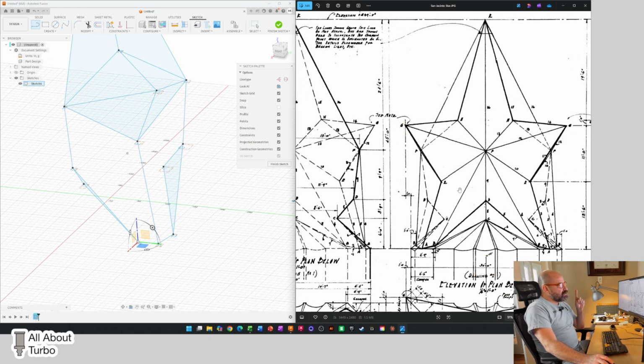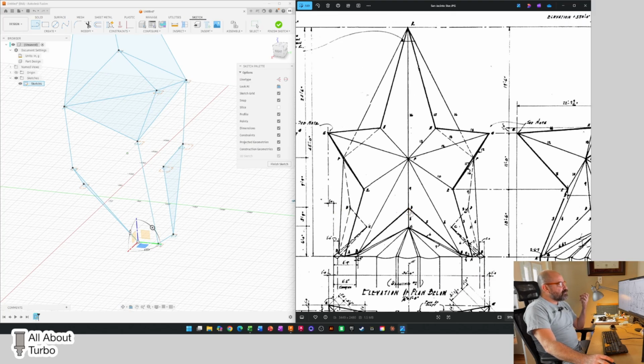And this is the only thing I would think, I don't want to call it a flaw, but when you look at this leg, the points A, B, F, E, there are 4 points. It's a trapezoid, not a triangle. It's the only feature in this drawing that is showing up with 4 points. Now, based on fundamental geometry principles, you need 3 points to define a plane. And if you add a fourth point, you start getting in trouble because that fourth point, unless it's on that same plane, is going to be off the plane. And that's what happens here.